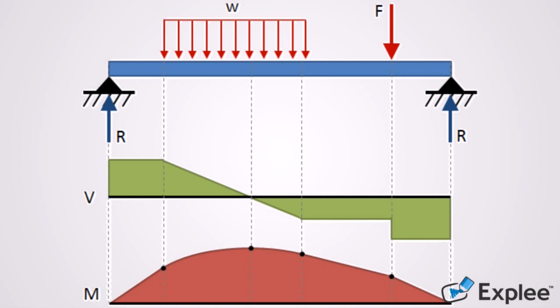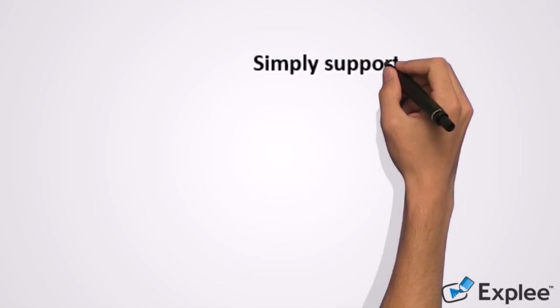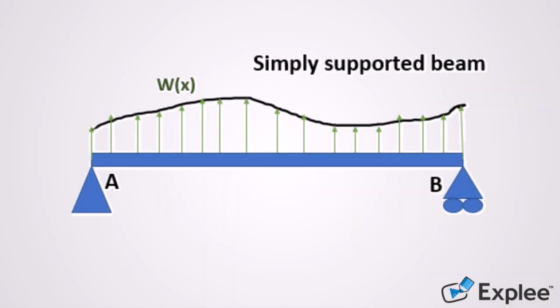Now, we can draw a shear and moment diagram very quickly if we can recognize some of the relationships between those quantities. Now let's say we consider a beam with a variable load. This will be any arbitrary load, let's say some load W. It can be of any magnitude, and this load is drawn positively, meaning it is going upward.